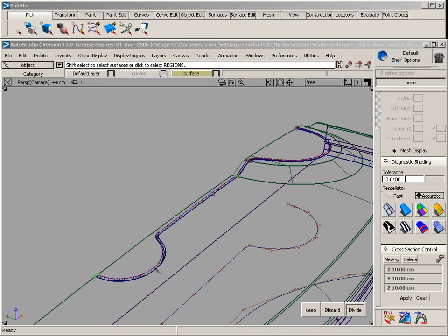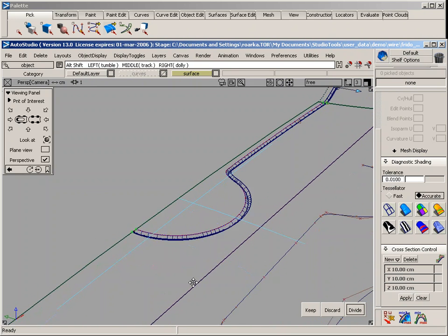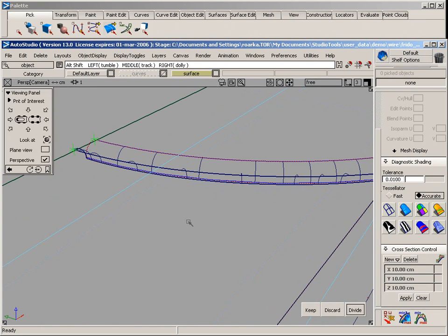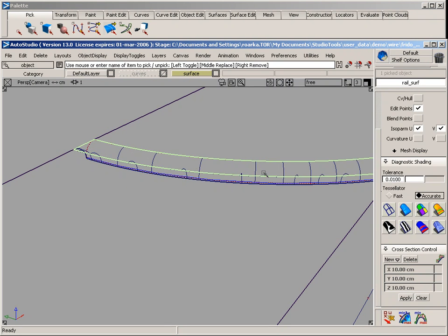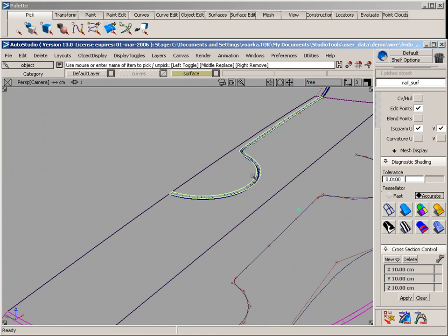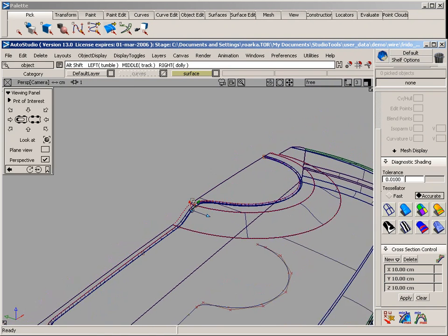Trim surface. Click on this area, the outside area, and to choose the in between, I'm zooming in here so I'm really sure that I'm selecting the right thing. Now for this, if this works, again choosing an object in this case works because this was a different surface type on how I created the original one, which was a rail. I can delete this one.